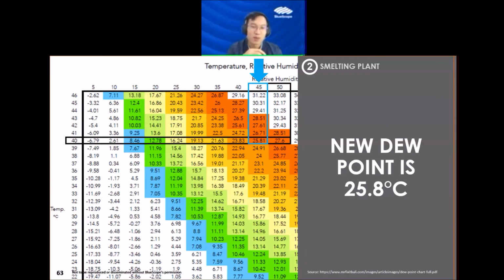If you are using a type of fastener, then my recommendation is, if you are looking at class 3 and class 4, those normally refer to the corrosion resistance of the fasteners against external weather. But if the internal weather is humid and you have condensation happening all over the fastener, you will soon have a risk of the fasteners corroding on the shank or locking area as well.